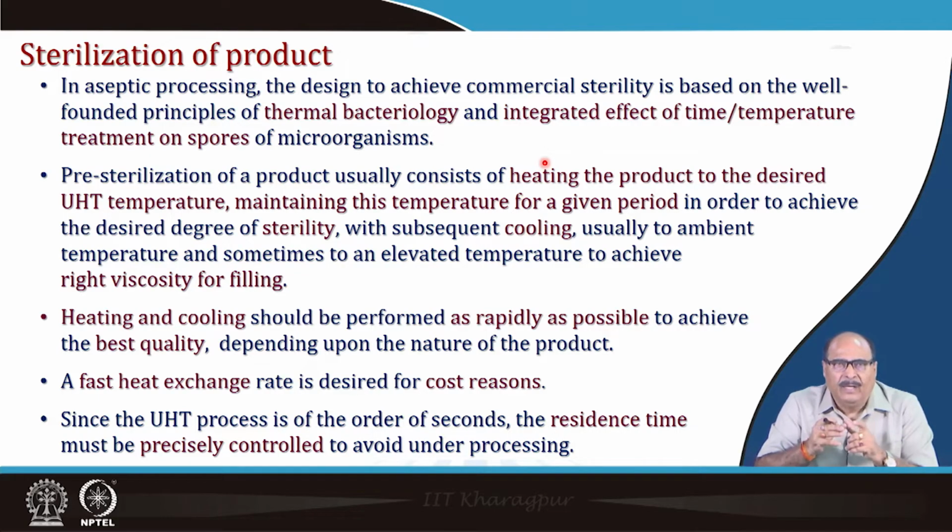So, heating and cooling should be performed as rapidly as possible to achieve the best quality, depending upon the nature of the product. A fast heat exchange rate is desired, and since the UHT process is of the order of seconds, it is very important that the residence time, particularly the residence time in the holding tube, be precisely controlled to avoid any under processing or over processing.